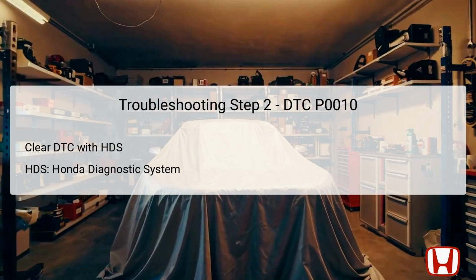In the second troubleshooting step, clearing the DTC involves using the Honda Diagnostic System, HDS, to reset the vehicle's onboard diagnostic system. The HDS is an advanced diagnostic tool that interacts directly with the vehicle's computer, allowing technicians to clear DTCs and reset any malfunction indicators related to the VTC system.